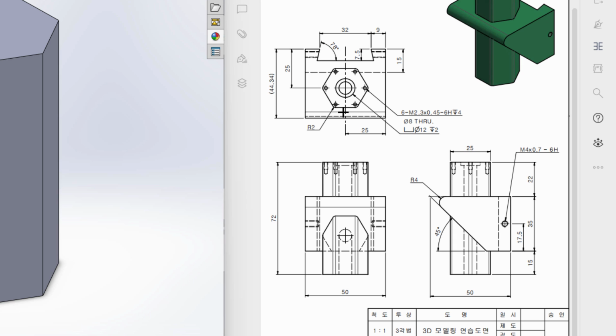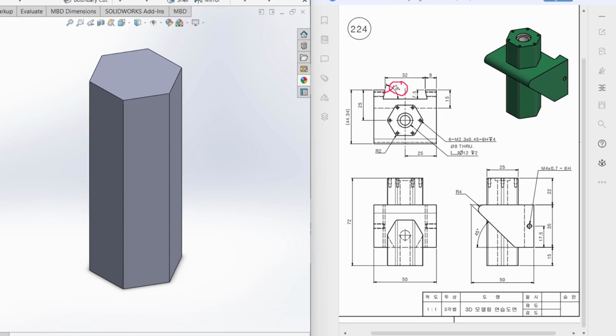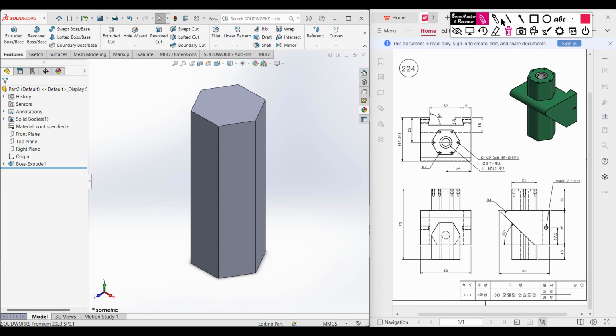Okay, and later on we can see we have another cut here, trapezoidal cut. And for drawing this trapezoidal cut, I'll take a midpoint line from here to here, and this midpoint line has a dimension of 32 unit. Then I'll take another vertical line of 7.5 unit, and from that I'll draw another midpoint line and draw two incline lines. As the incline line, we can see it has a dimension of 78 unit. So here to here the dimension will be 180 minus 78. Okay, so let's go back to our SolidWorks.